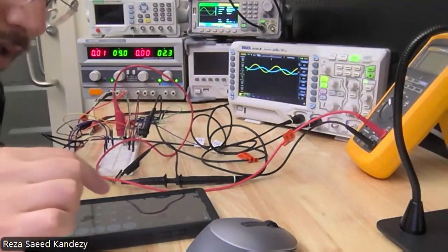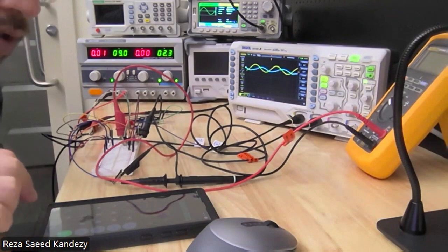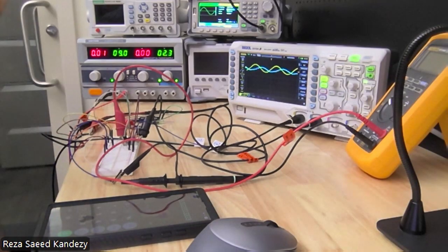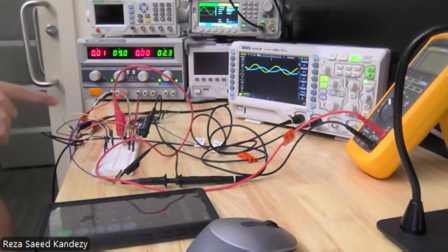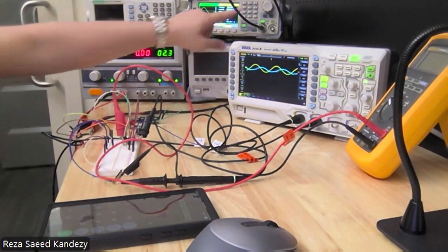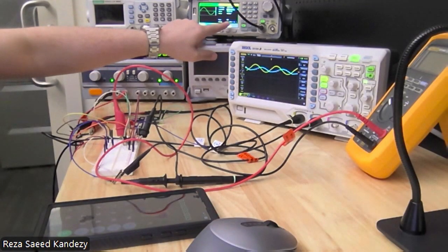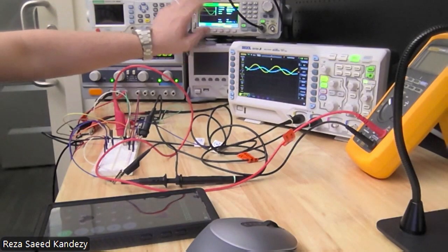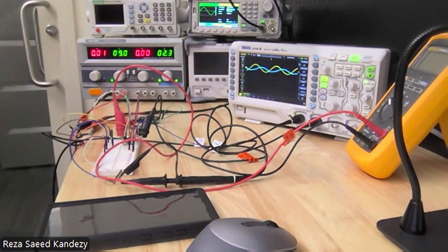So let's divide those. I have a 3.33 gain, and my load is also 1K. My source is 3 ohm, and the inside impedance of the signal generator is 50 ohm. So it's the same situation that we did for our small signal analysis at the end of the last part.